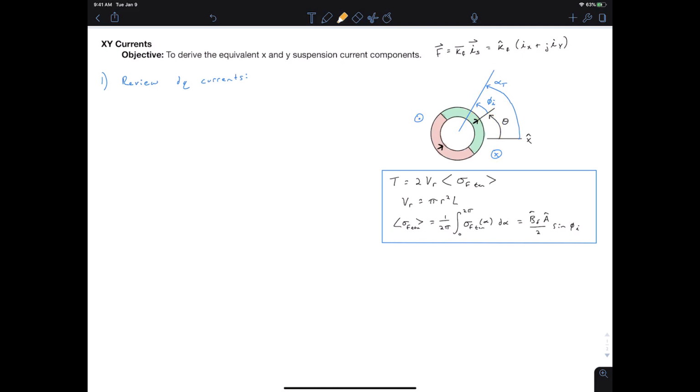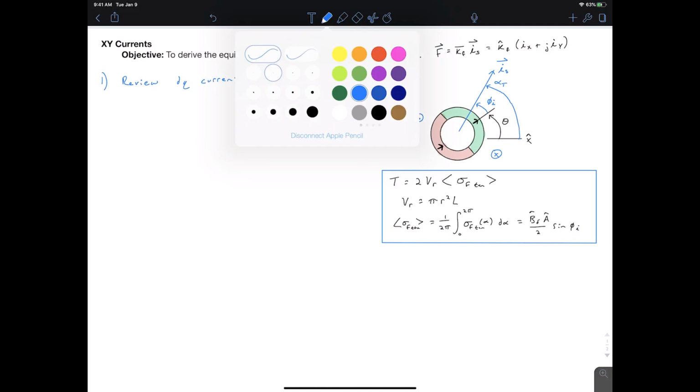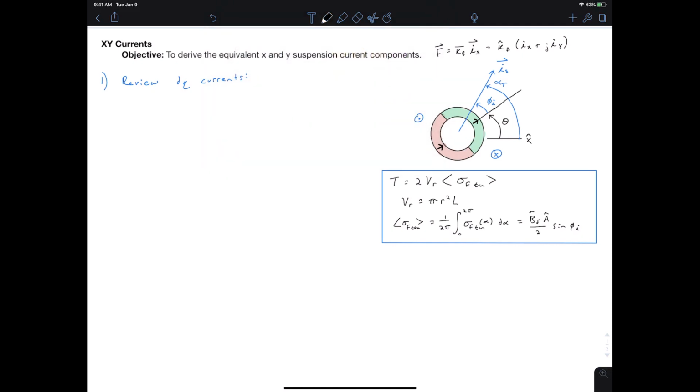As we've been talking about in previous videos, this alpha t is also the angle of our current space vector. So this blue line here, we can simply indicate that this is also the location of a current space vector. It has angle alpha t. And so when we talk about motors having a direct axis, we can also say that they have a quadrature axis. This means something both physically for the motor as well as for our current space vector. The direct axis is always the location of the north pole, and the q axis or the quadrature axis is the location in between the poles.